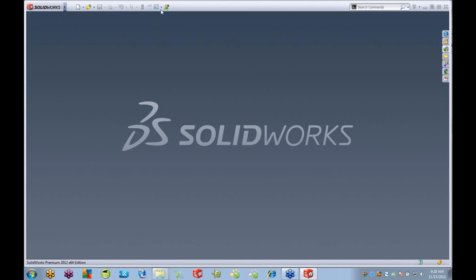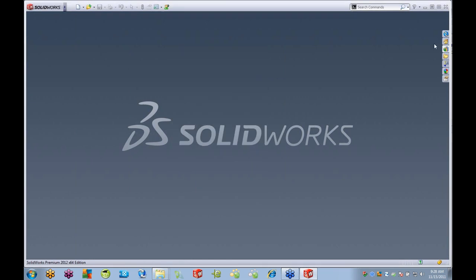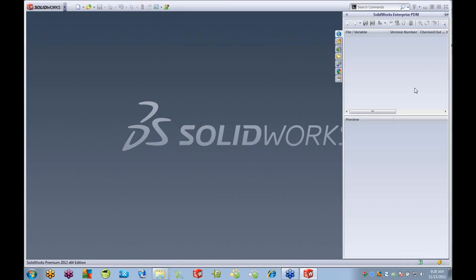Inside of SolidWorks, you're going to have an add-in for Enterprise PDM. That add-in shows up in the task pane. Now, a lot of the functionality that you see me performing in Windows Explorer can also be done inside of the Enterprise PDM client. Now, John mentioned that out of the box you get several CAD integrations. Some of them have their own add-in that can perform check-in, check-out, change state, getting access to the data card, searching, performing a lot of the functions that you would use inside that Explorer window that I just showed you.